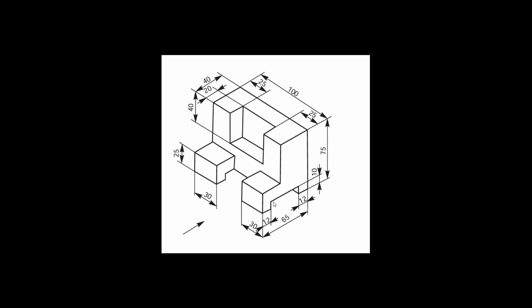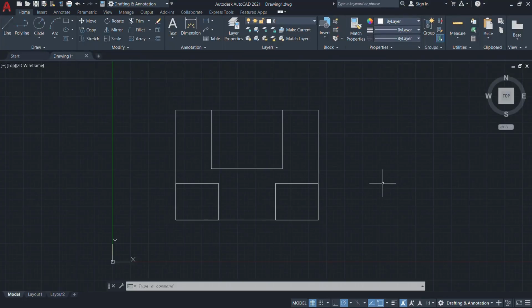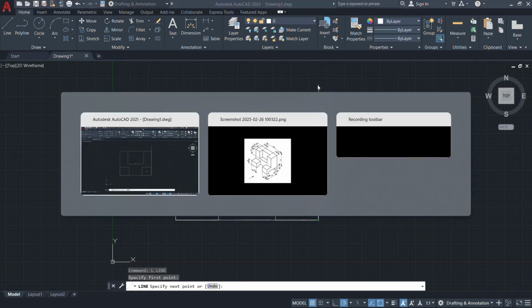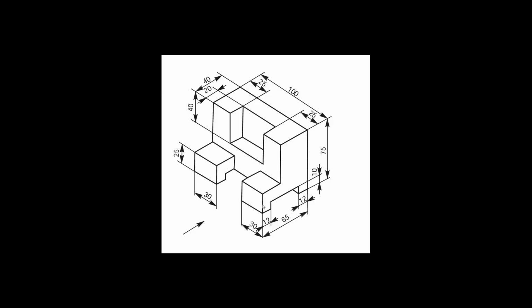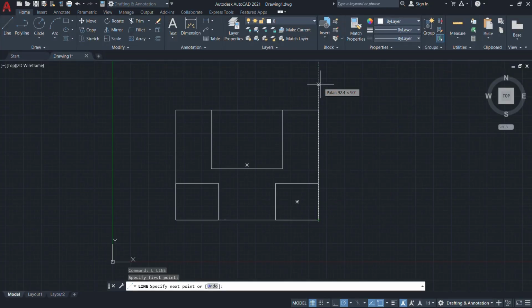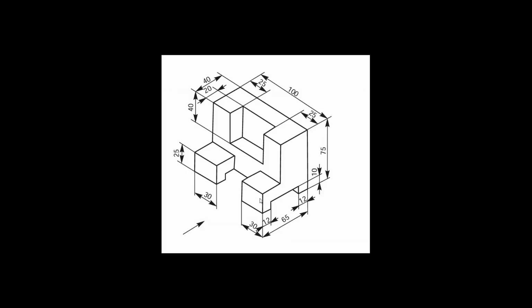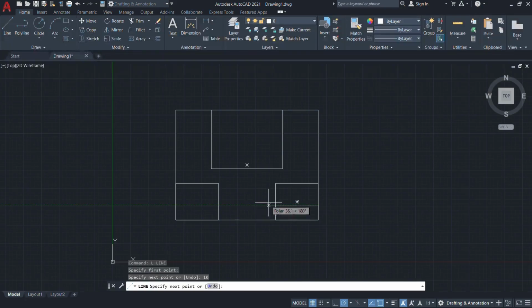There is a rectangular pocket portion under this overall solid body. Now draw these areas also. First, selecting this right hand corner, draw one vertical line. It is a dimension of 10 mm vertically. So mention 10 mm now. And draw one horizontal line profile up to a distance of 30 mm, same as how it is represented on this 3D model drawing itself. So mention a 30 mm horizontal line profile.